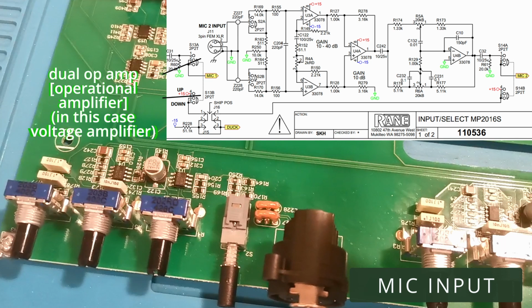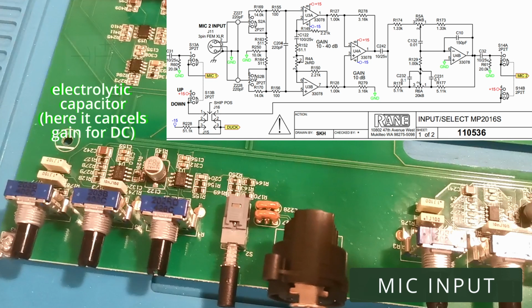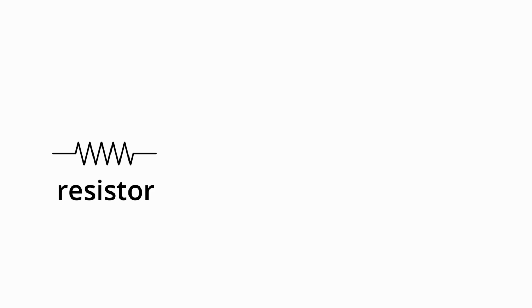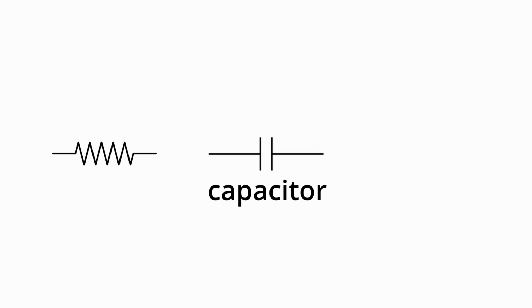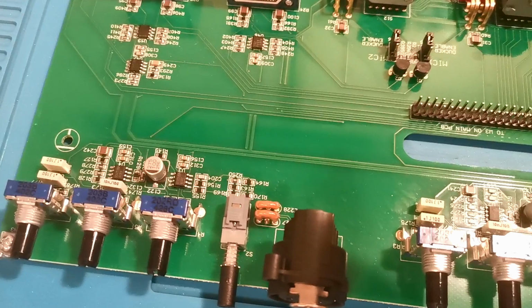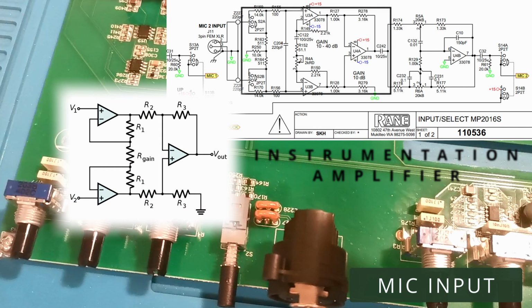This mixer is IC-based and uses operational amplifiers. Op-amps are high-gain amplifiers with differential inputs and have a very wide range of applications. Potentiometer is simply an adjustable resistor. Thanks to this we can set the gain of amplifier. Next we have electrolytic capacitor, here it's used for DC blocking, and a film capacitor setting the time constant of the EQ filter. Resistor, capacitor, operational amplifier. Understanding those elements means understanding this mixer. Most circuitry here is based on various combinations of those 3 elements.